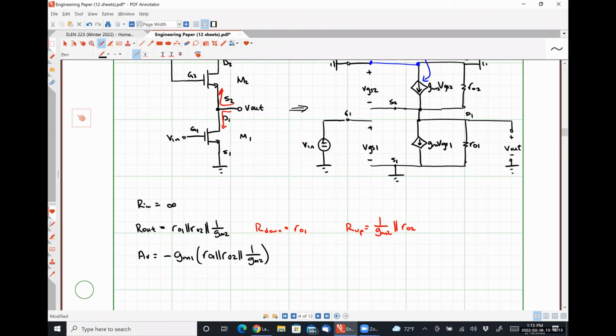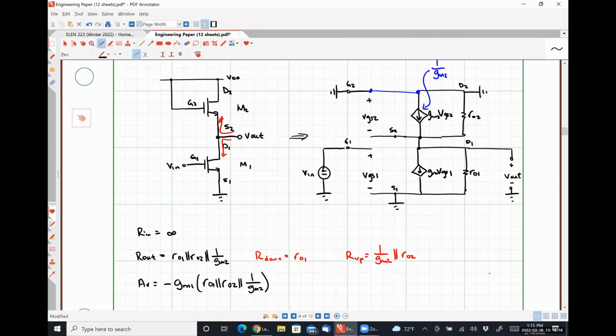Because the reason why we use these guys is because they behave effectively the exact same way as a resistor does, or a combination of resistances in this case, at small signal, but at large signal, they don't cause that large voltage drop that a DC current flowing through a DC resistor will, okay? Which gives us more of what's called headroom. And for those of you who suffer through ELEN 438 with me next fall, we'll go into gobs and gobs of detail about trade-offs and all that kind of stuff that we can do. All right.